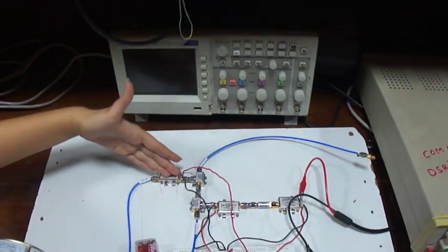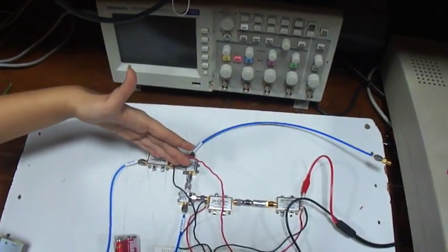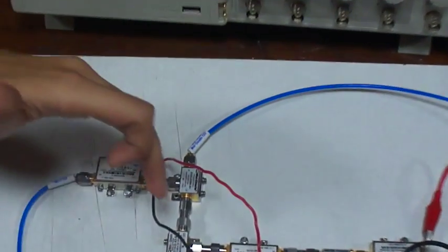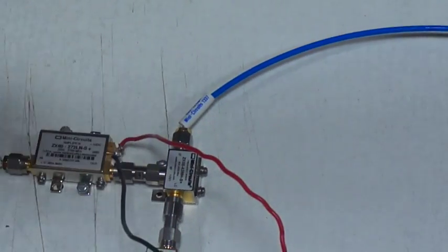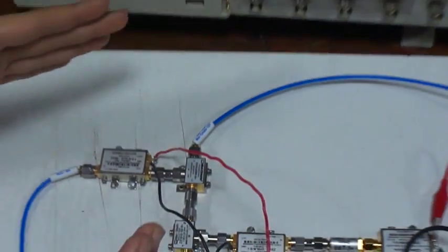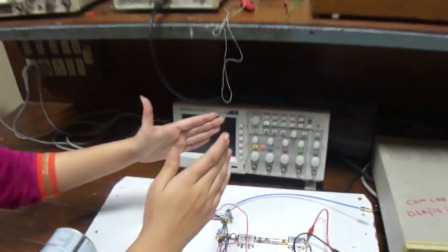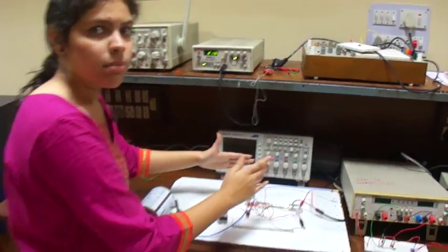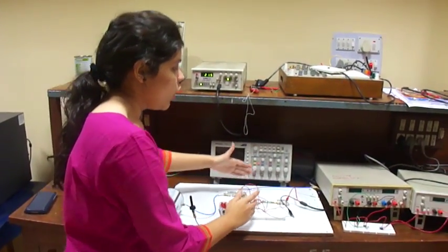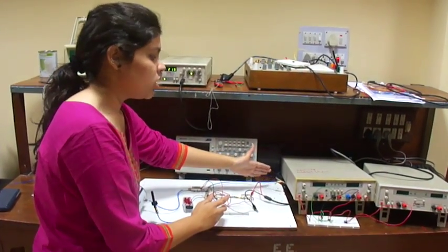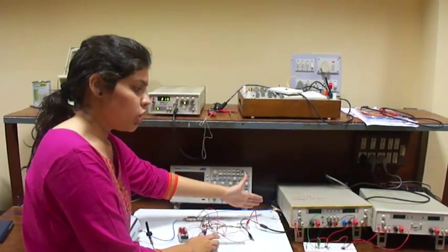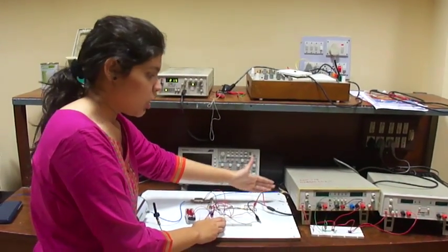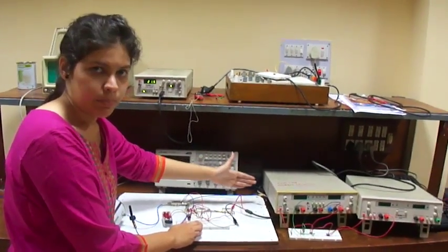This amplified signal is then fed to the mixer, whereas the mixer's other input is what was transmitted. So the mixer gives us a difference between the transmitted and the received signal, which here can be displayed on the digital storage oscilloscope and can also be used to create an alarm.